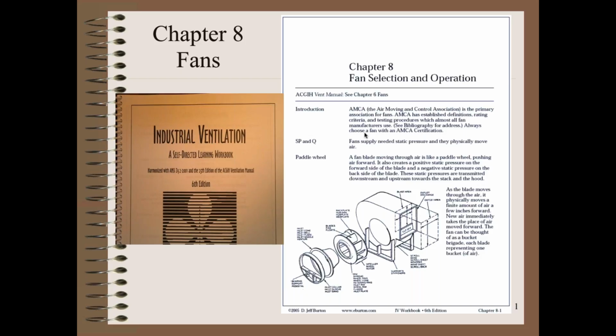This positive pressure, you're going to start from the fan and work your way out to decide what that's going to be. So at the end of this, what you're going to wind up with is, I need 4 inches of negative pressure here. I need 2 inches of positive pressure here, right? And so I'm going through here. There's a change in pressure that this is going to deliver, and I have to move Q. I have to move 2,000 cubic feet per minute of air.